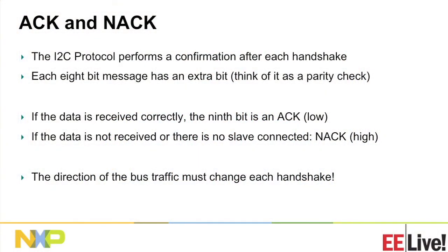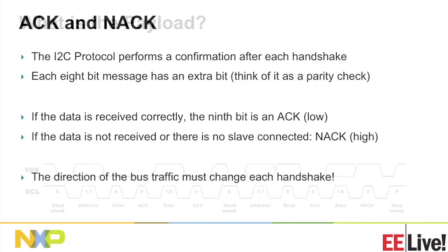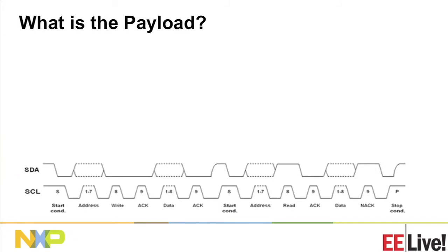So some of you may be aware that there are buffer, repeater, or extender devices that can be used to extend a bus beyond its normal range. These devices have to be able to change direction without an external direction control pin. Okay.